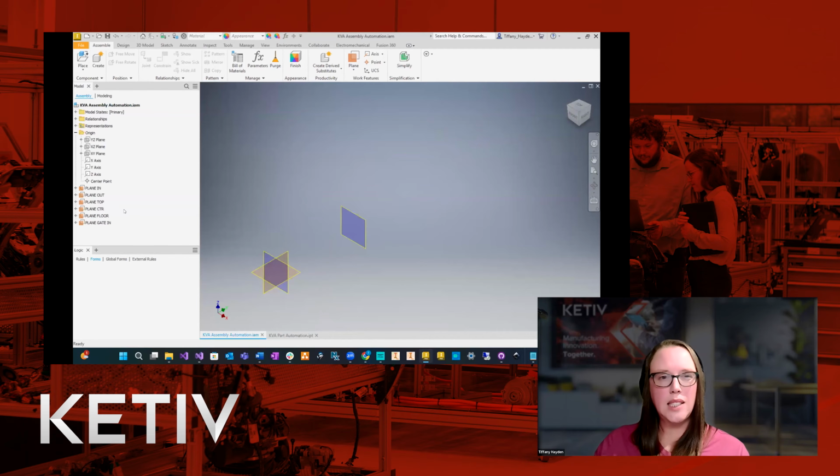It's always good practice to make sure your work planes are going in the right direction. I don't know how many times I have accidentally not put a negative when I needed to, and it just reversed the direction. And then, why are my components in weird places? It's really good practice to just zoom out and see where it is before you accept it.